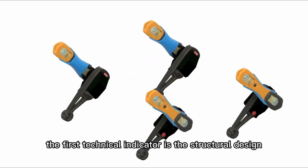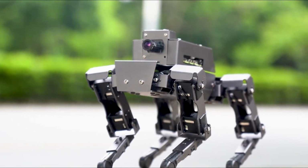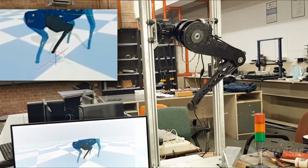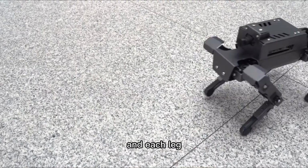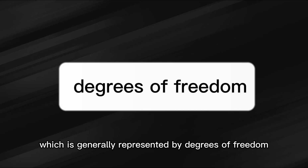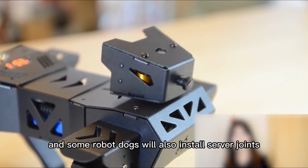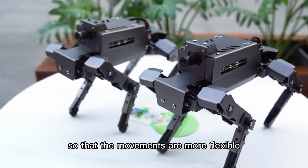The first technical indicator is the structural design. The adaptability of different structures is different. The main structure in the robot dog is the 4 legs, which can be divided into parallel legs and tandem legs. The range of motion of the tandem legs is wider, and each leg also needs to be embedded with a steering gear, which is generally represented by degrees of freedom. 8 degrees of freedom generally means that one leg of the robot dog has only 2 joints, which are the leg and the shoulder, and some robot dogs will also install servo joints on the head or waist tail, so that the movements are more flexible.